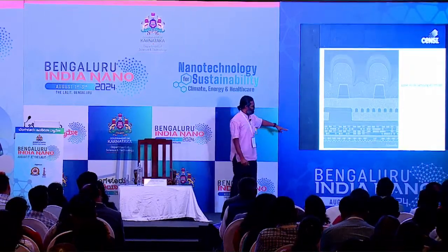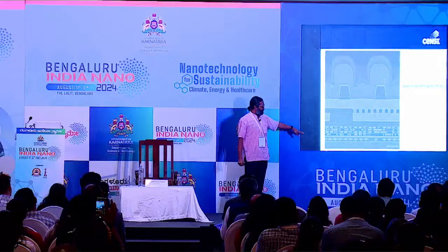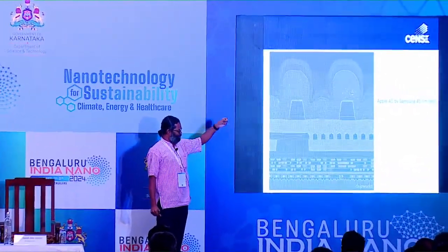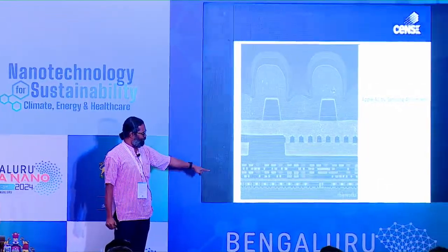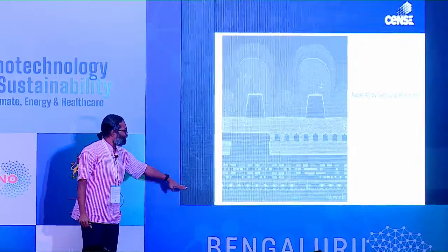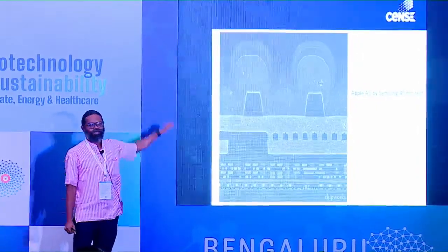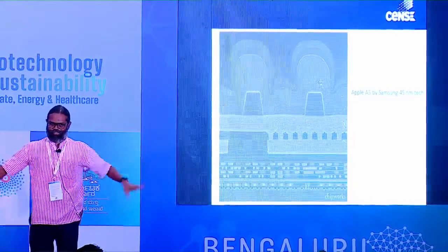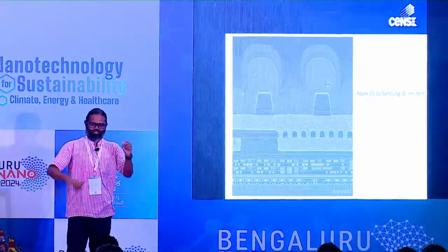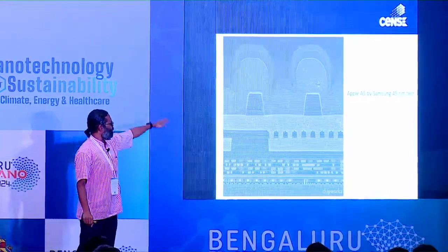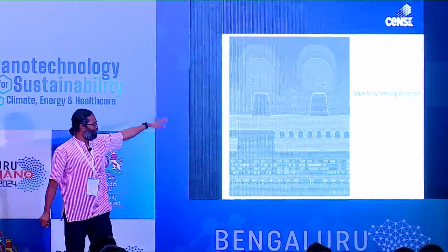And the transistors are sitting at the bottom, right? The transistors, the bright and dark small pegs that you see, those are all isolation lines. The transistor is right at the bottom, and whatever you see up to the top is just connecting them, all right? It's like you have the active region at the bottom, and then you start wiring these devices, which is what we do across all these layers.